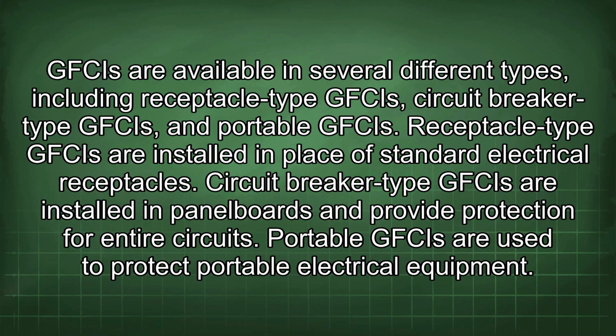Receptacle-type GFCIs are installed in place of standard electrical receptacles. Circuit breaker-type GFCIs are installed in panel boards and provide protection for entire circuits. Portable GFCIs are used to protect portable electrical equipment.